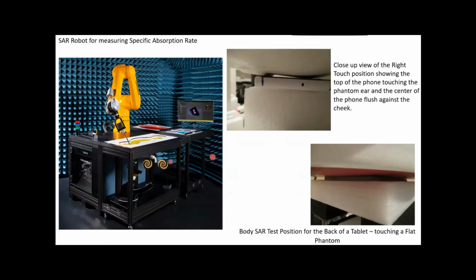Then there are some quick pictures on how you measure SAR. We have what we call a DASY6 here. This is a robot that we have in a lab. It's not our particular robot, but it's super similar. It has an E-field probe that goes into a liquid that simulates your body's properties, the dielectric constant and the loss tangent of your body. It's simulated by this liquid.